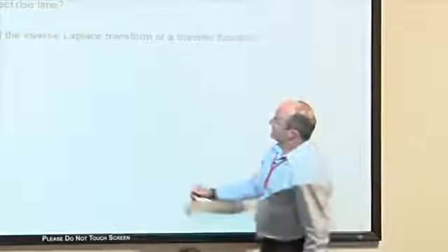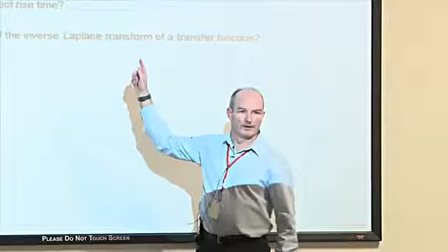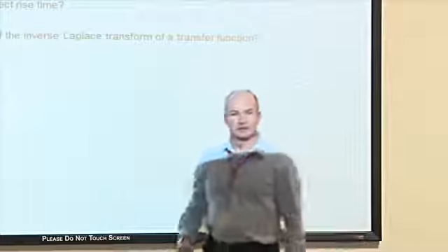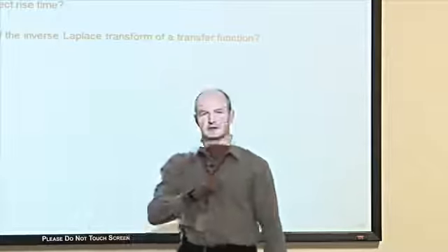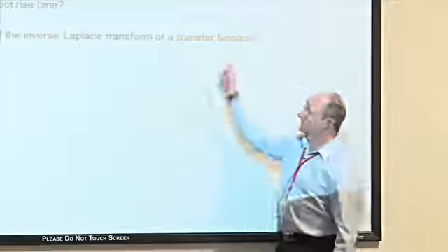Great. How does a right half-plane zero affect rise time? Well, it's 50-50, isn't it? It's only going to make it longer or shorter. Right half-plane zero, rise time is longer? Right half-plane will give you undershoot, but the rise time will be longer. A left half-plane gives you overshoot and shorter rise time. So the answer is longer. What is the significance of the inverse Laplace transform of a transfer function? What does that mean? Impulse response. If you take a Laplace transform of an impulse response, you get the transfer function.